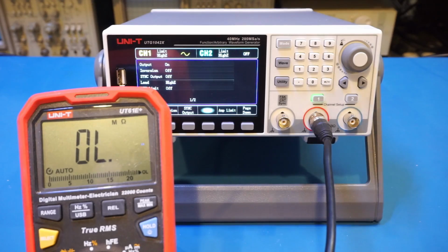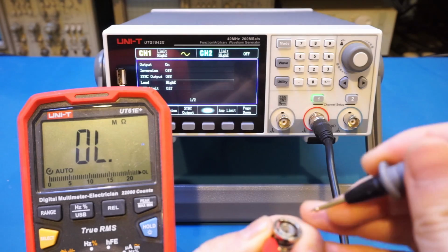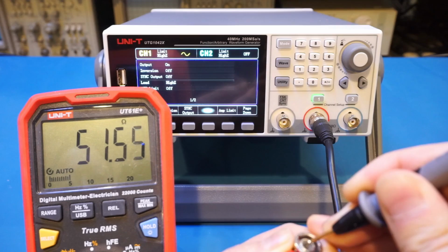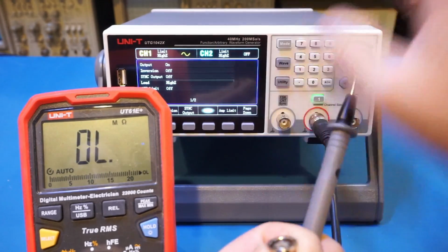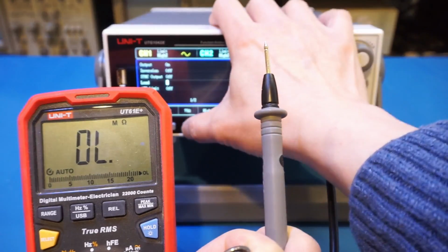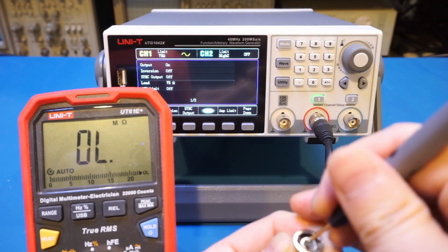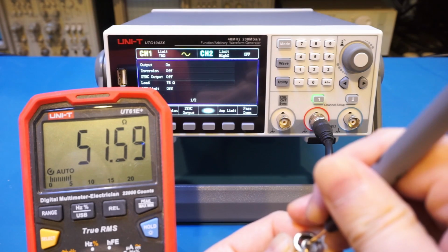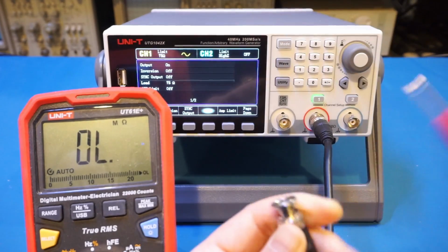So you can see we're doing the ohm measurement on the output here. Let's do that. You will see that the actual output impedance is roughly 50 ohms. Right now we're at high Z, so let's change that to, say, 50 or 75 ohms. And you can see now we're showing 75 ohms, but the output is still at 50 ohms. So basically the output is always 50 ohms, but the software adjusts its output so the displayed voltage matches the intended load.